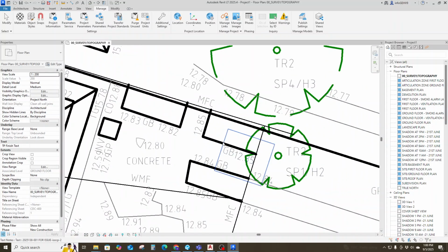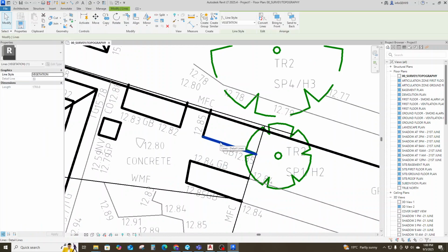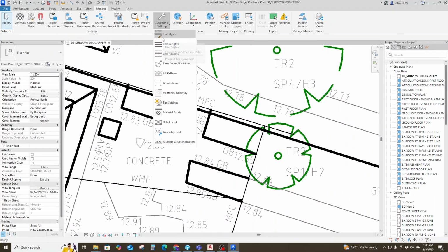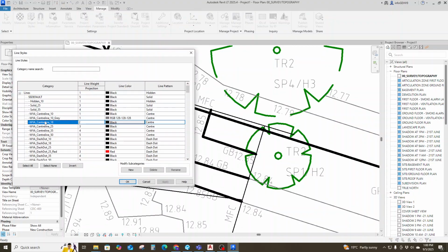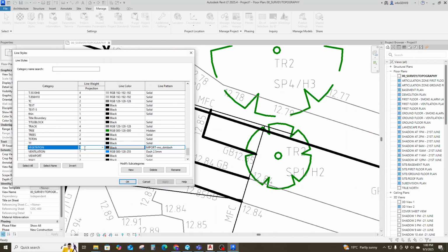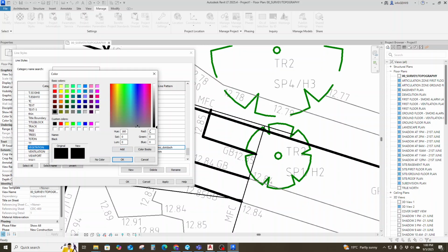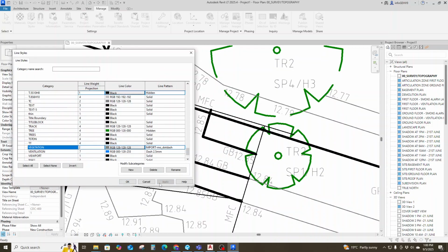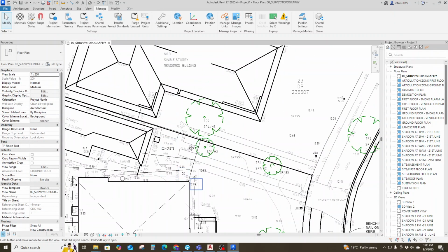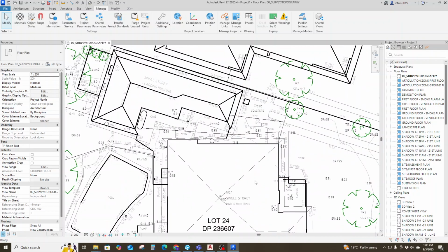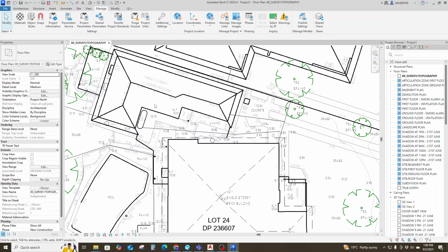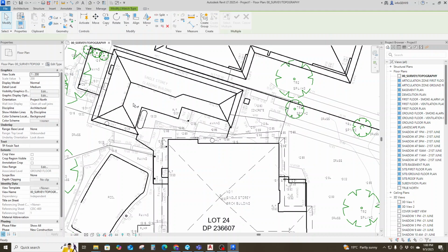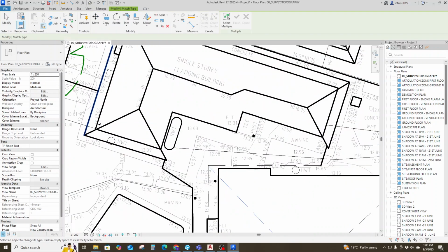Okay, then these lines are almost the same as this one. This one is vegetation, so we don't want them thick. We want them smaller as well. So we go to line and then vegetation, and all of this is 5. This will become 128, 128, 128. Say apply. The other way, which I told you earlier, was to match the properties of the roof. So you can just select this and start making it cleaner.